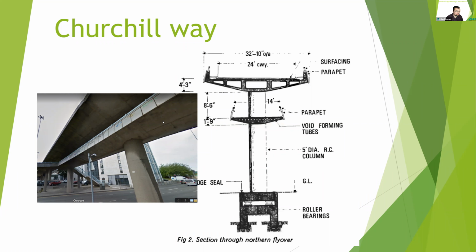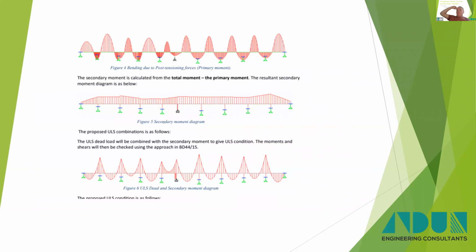Okay. So this was a pair of 230-metre long post-tension viaducts in Liverpool city centre. They were continuous. Continuous post-tension structures are even more of a pain in the backside to analyse, because you get parasitic or secondary moments due to the post-tension effects. Again, I'm not going to go into detail on that here. Suffice to say, it gives you a bit of a headache.